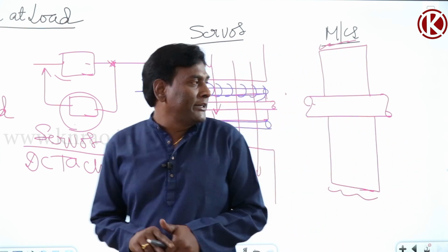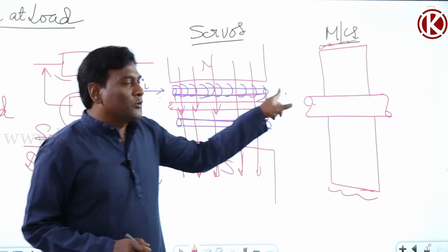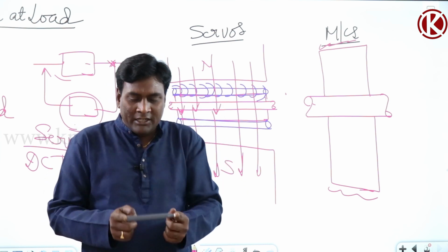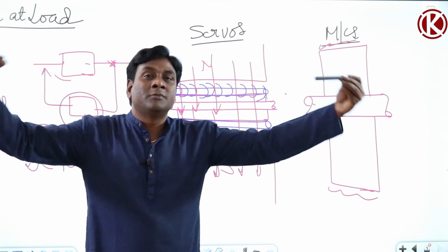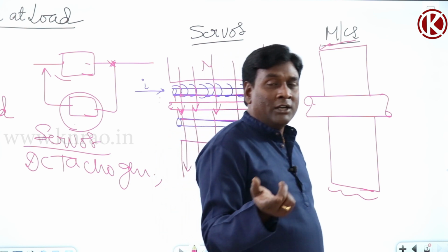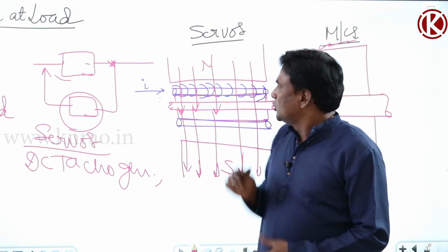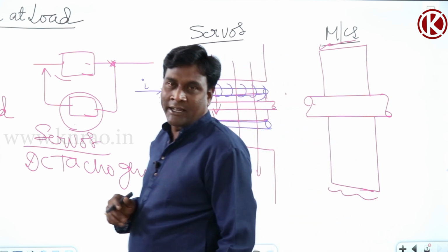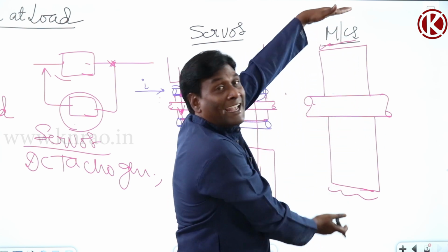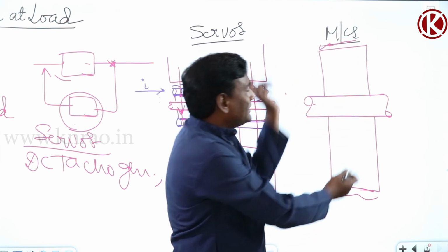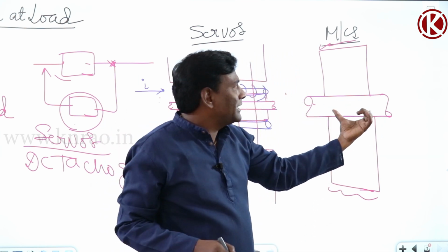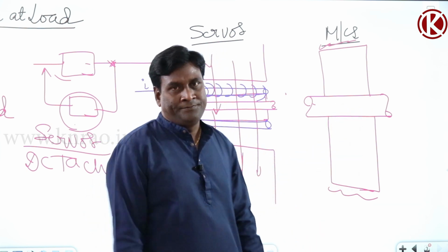Now coming back to the point, if you increase the active length, automatically the torque developed will be more compared to the shorter length. So the torque by weight ratio will be more, such that the time constant will be less. Let me come back again. In machines we are going to reduce the shaft length and increase the diameter of the rotor, and shaft length will decide the cost of the machine. The price of the machine can be reduced by reducing the length of the shaft.